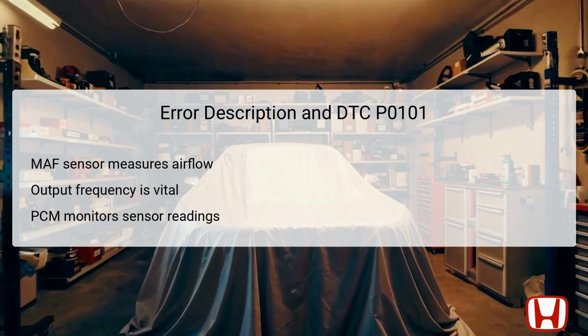The PCM continuously monitors data from the MAF sensor to ensure that it operates within specified limits. If the frequency deviates from the set parameters, the PCM identifies this as a malfunction and stores the DTC. This situation can stem from various issues, including sensor failure, wiring problems, or obstructed air intake components.